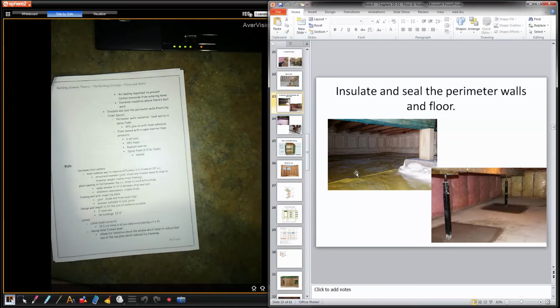So floor meaning the mud, not up here. This is the old-fashioned way of doing it, right? So you frame up a 2x4 wall in a crawl space. Looks like there was a change of plans here. They had to cut up the floor, put in new footing to support this beam. Maybe this floor was sagging, so they went in and put a new beam in, footings.